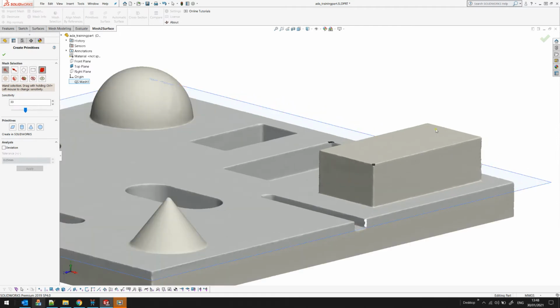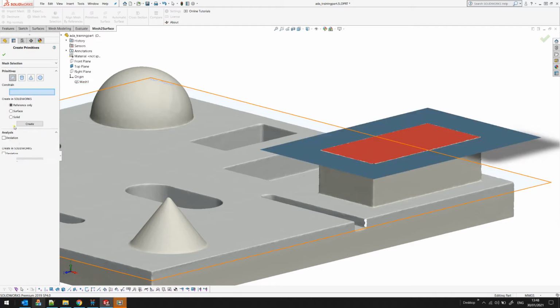I'll use my selection tools and will click on the mesh, and the software automatically will select based on the curvature. Next step I need to do is just press on the icon which is for fit a best plane. What happens now is that the software uses algorithms to find the best fit through the points that belong to the selected triangles. You can see the result on the screen shaded as a plane, and also you can always